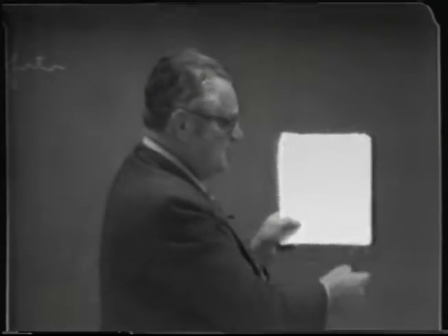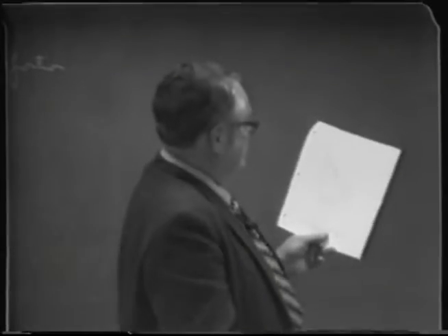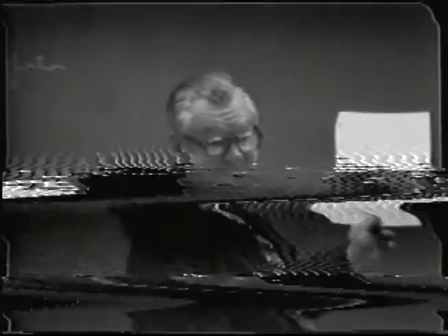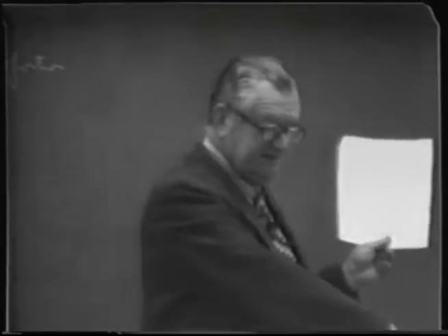Then the system was put into an equilibrium still, which I'll talk about a little more later, and the composition of the vapor in equilibrium with the liquid was experimentally determined. And then these values were plotted as a function of ethyl alcohol and water. So you see, this is a rather interesting set of curves from the standpoint of predicting the behavior of these alcohols during distillation